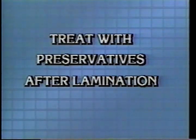Treatment with oil-borne preservatives, creosote or pentachlorophenol, should always be performed after the gluing or the laminating occurs. It is not satisfactory to laminate waterborne treated material after the treatment has occurred. There are problems with the adhesive systems in adequately adhering to the treated waterborne products.